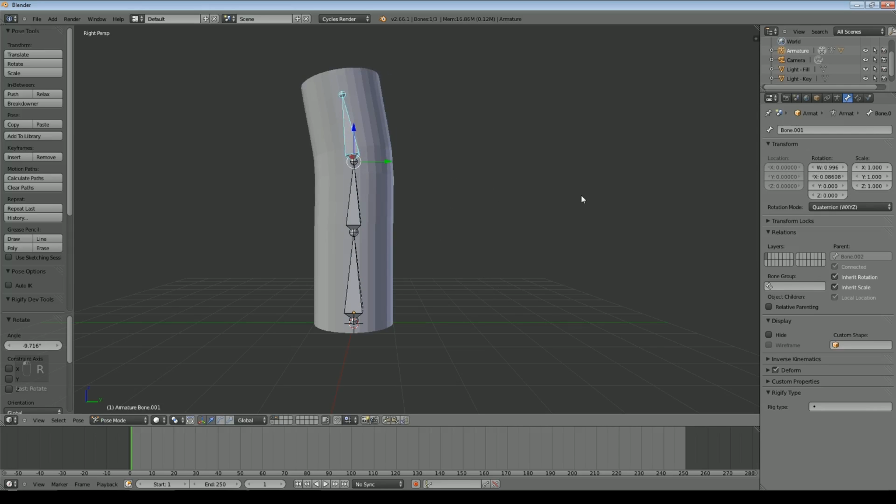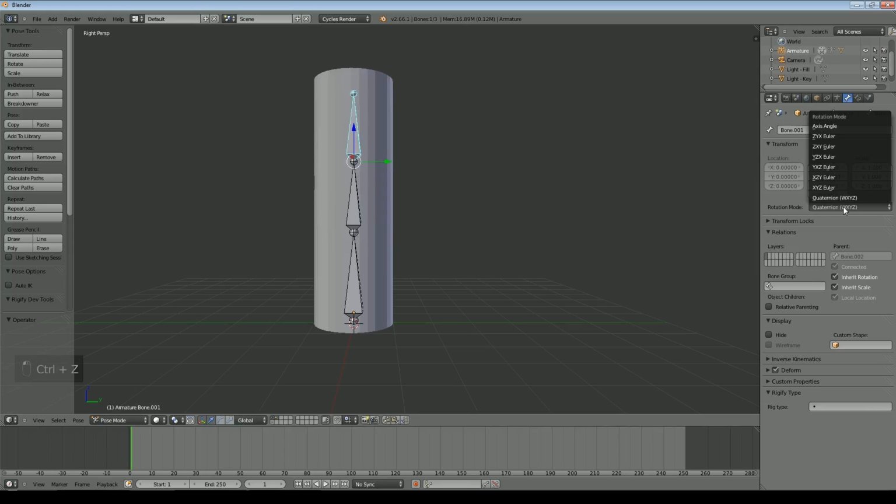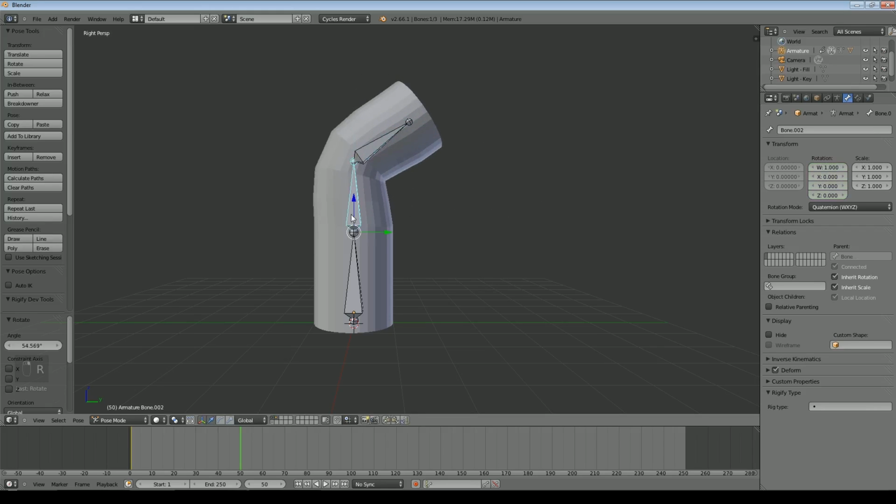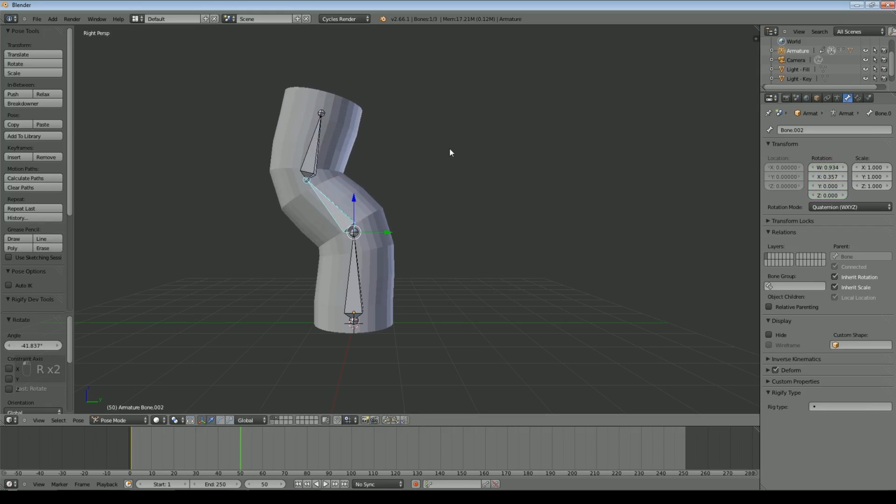The exact format for these parameters depends on what we select here, so you could just select that and then you get an X, Y, Z as before. But it doesn't really matter for our purposes. So I could, for example, keyframe that, then come over to the 50th frame, rotate, and perhaps rotate this one that way, keyframe that, and then come up to the 100th frame.